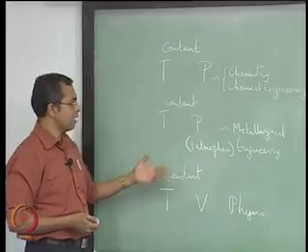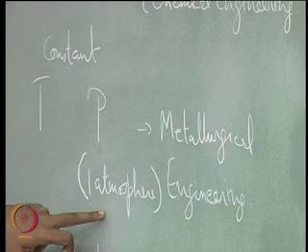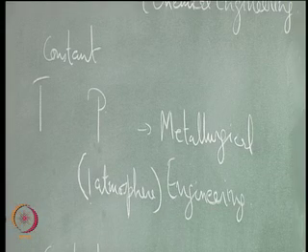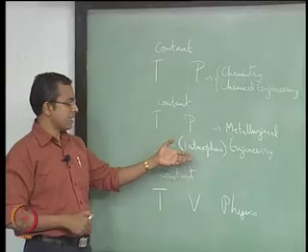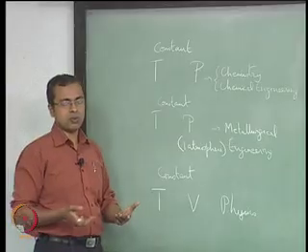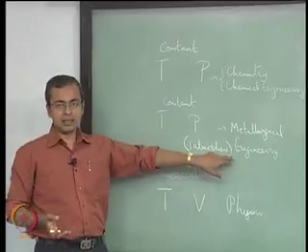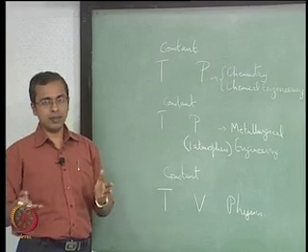So, that is what is being done, and in the metallurgical system, since it is typically facing 1 atmosphere pressure from our natural atmosphere around us, you end up finding 1 atmosphere to be the case. In fact, there are diagrams where the assumption is already 1 atmosphere. Okay. So, many of the phase diagrams that you will see associated with metallurgical engineering systems, you will only see temperature and composition in that phase diagram most often.